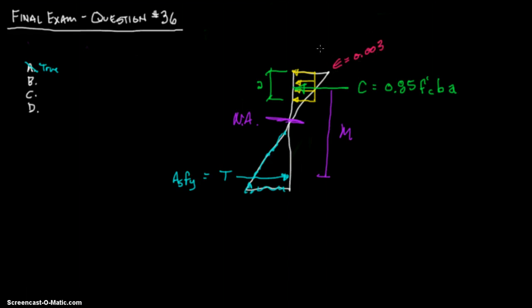So in concrete design, you have to keep this, and that's where you can deal with your reinforcing steel. You want your reinforcing steel to yield. You want to go over that before you yield your concrete. And I hope that makes sense.